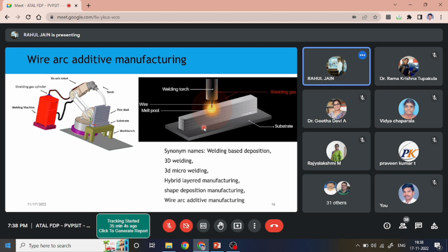and so forth, right? And if this system I attach with a robotic arm, let's say I have a 6-degree freedom robot, through which my wire feeder is coming. So if I have a 6-degree freedom robot, then instead of making this layer like this, I can make it circular, right? Or I can make it elliptical, or I can make some complicated shape which may not be possible for a human being to do manually.